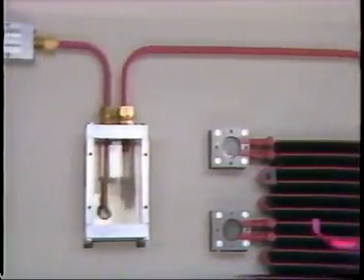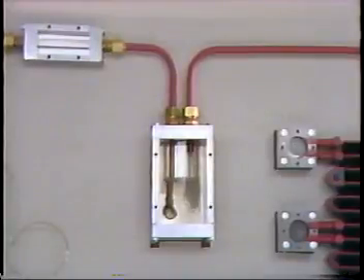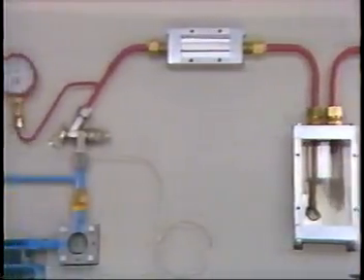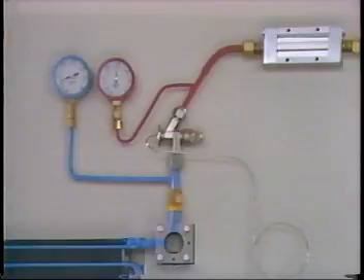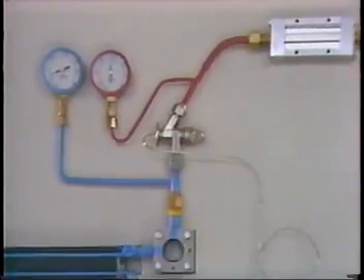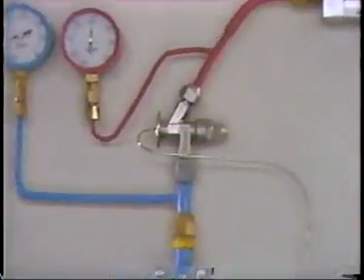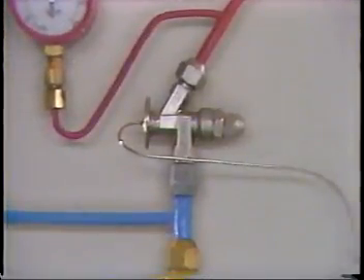The liquefied refrigerant is stored in the receiver and dryer unit. Dirt and water are also removed from the refrigerant by this unit. The pressure is reduced by the expansion valve. This valve also adjusts the amount of refrigerant supplied to the evaporator. Then the refrigerant again takes heat away from the air in the passenger compartment as it is turned into a gas by the evaporator, and the cycle starts over.